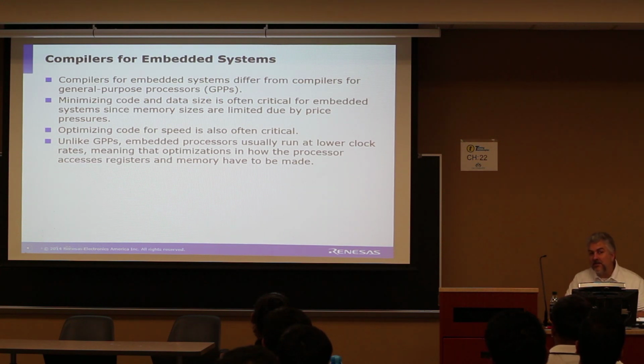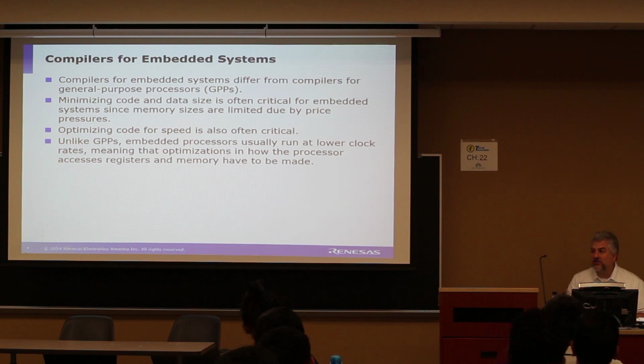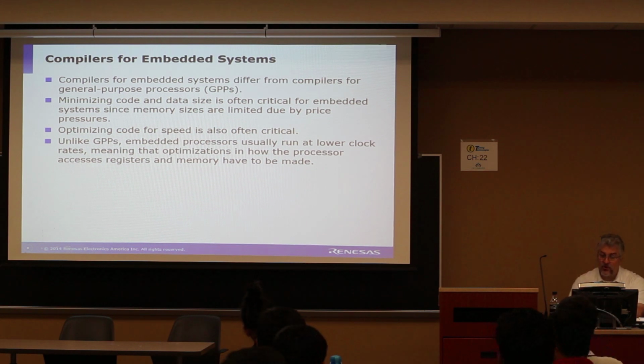The maximum would be 100 megahertz for the clock speed for your processor. So that would require a 12.5 megahertz crystal. So with the board that you have, the clock itself for the processor runs at 96 megahertz. That would be a really good test question or quiz question.